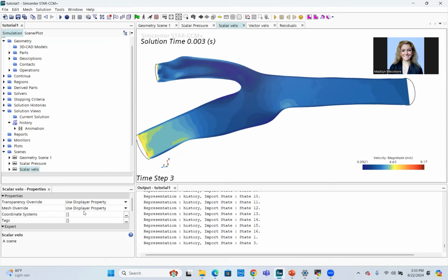No, you're good. I'm just trying to think through what I've given values to. See, there's the mesh size. That's a value. Boundary conditions. I didn't give these boundary conditions a value though. Here's my stopping criteria, where I set it to 1 times 10^-6. Maybe it was the mesh size. Was that the last one that you did, like 5 and then you put it down to 1? Talking about the number of prism layers?